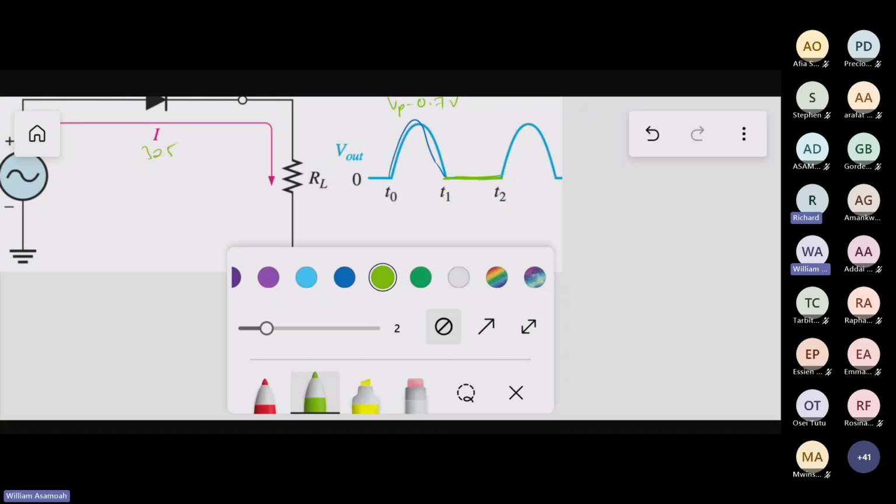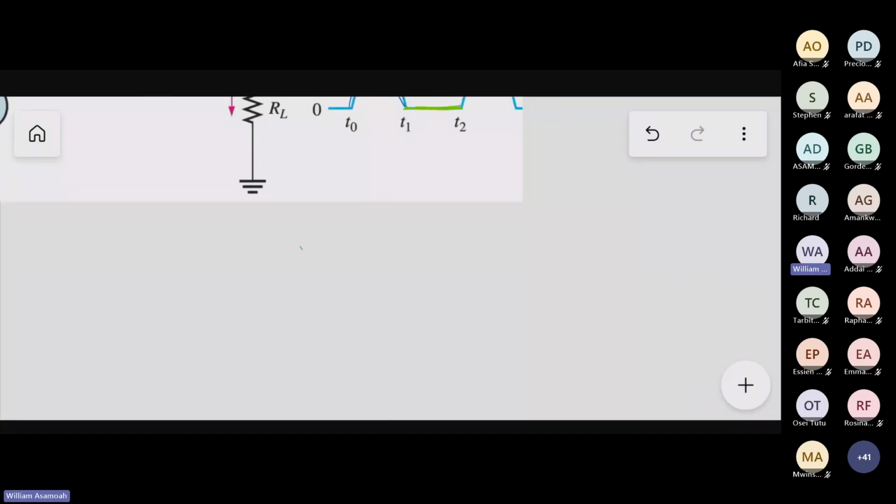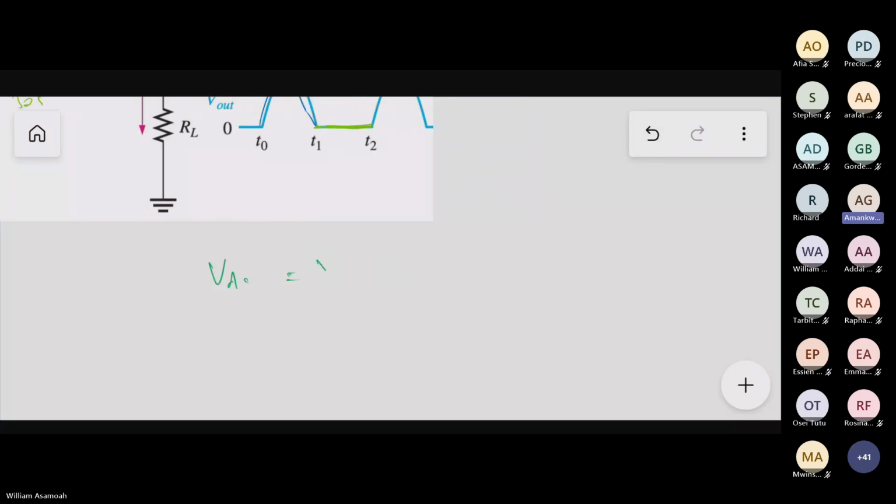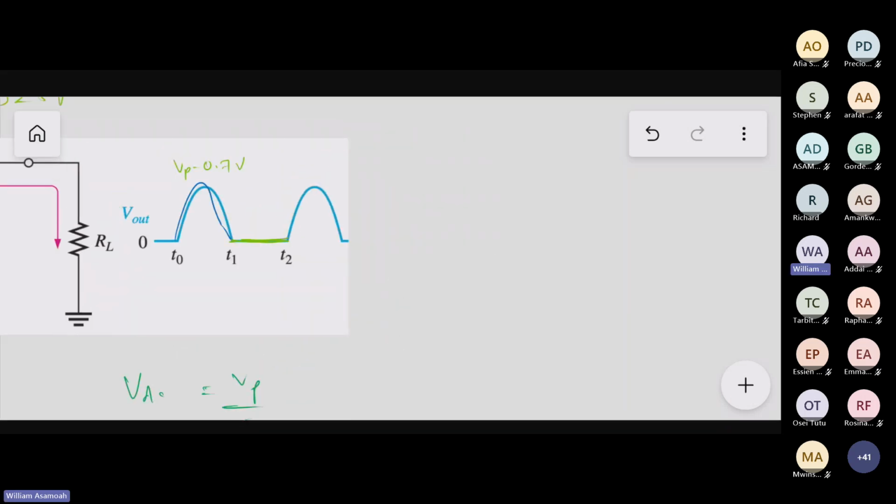If you rectify a half wave, the average value of DC that you get is equal to V peak over pi. V peak over pi for a half wave. So let's take example 4.5. Find the average voltage of the half wave signal below. So the average voltage of the half wave signal, and he showed us a half wave signal of,